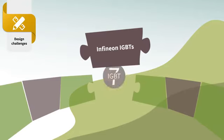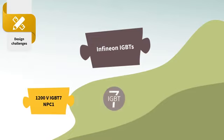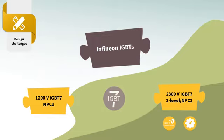Infineon developed two IGBT technologies to meet the market needs. The 1200 volt IGBT7 in dual configuration to build the NPC1 topology, which aimed to decrease the system costs and allow a performance optimization with minimal design changes, keeping the state-of-the-art power level of 1.1 MVA. And the 2300 volt IGBT7 in a simple two-level topology or an NPC2 topology in combination with a 1200 volt common collector configuration, which aimed to address the next level of power and performance but with a change in the inverter's topology.